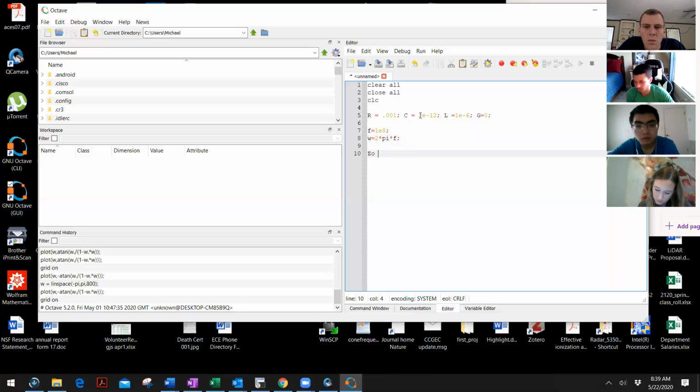So Z naught is equal to the square root of R plus 1j times omega times L over G plus 1j times omega times C.